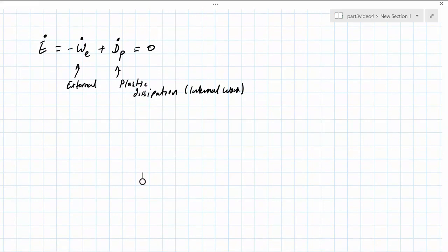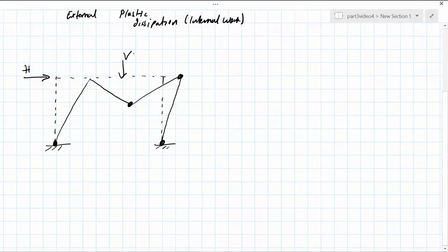An important aspect of this analysis is the consideration of deformations and displacements. Generally, the energy balance can be depicted in the following way. Firstly, we wish to identify the displacements caused by the externally applied loading. The first such displacement is underneath the horizontal load. We indicate this as lowercase delta subscript B H.